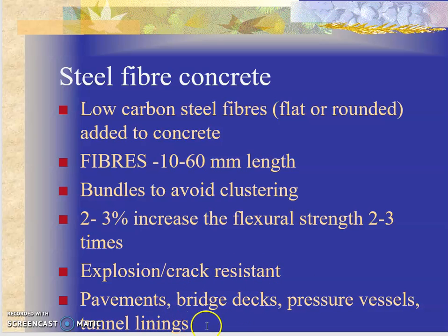Now again, these are also used in pavements, deck slabs, okay, bridge decks, then the pressure vessels and tunnel linings. Okay, tunnel linings also require very high strength. You don't want water to be pouring outside. Tunnels are obviously constructed in very hard rocks. Okay, and very hard rocks are many times fissured. There are cracks, so there is water flowing inside. So many times you require good grade and very high strength concretes with good abrasion resistance properties, so as the permeability and the seepage of water is controlled.